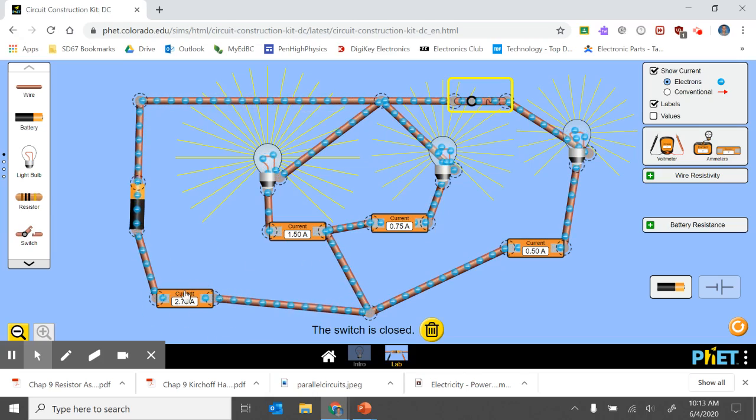So when you are wiring things in a home, that's why there are very specific rules for how many different outlets or light bulbs or fridges or other electric loads that you can put on a single circuit. And remember, in your home, each circuit is tied to a breaker. So there are limits to how many electric loads you can put on each circuit, because as you put more and more loads, you add more current to that circuit, and eventually your breaker will trip. And if you didn't have a breaker, eventually your house would burn down with too much current flowing through it.